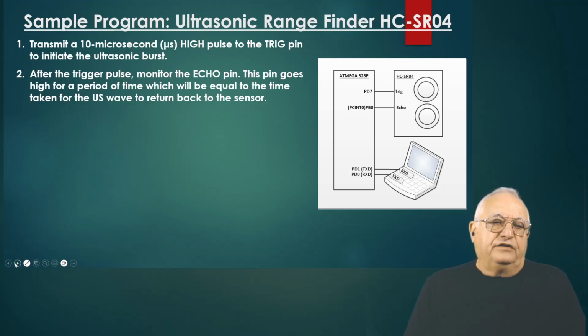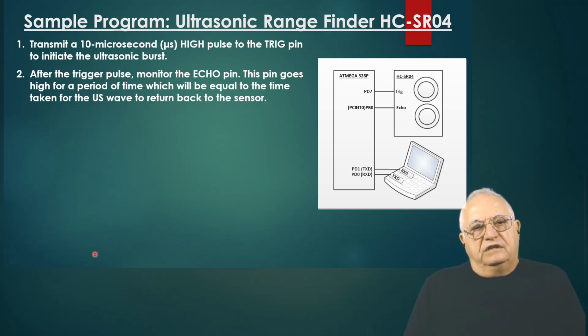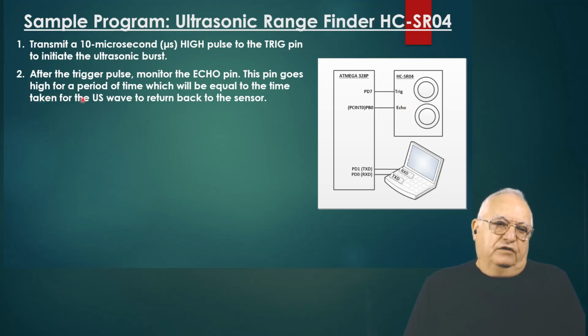Next, after the trigger pulse, we monitor the echo pin. This pin goes high for a period of time which will be equal to the time taken for the wave to return back to the sensor.